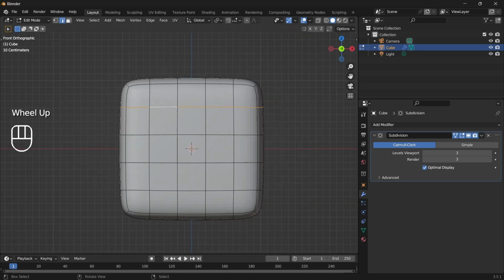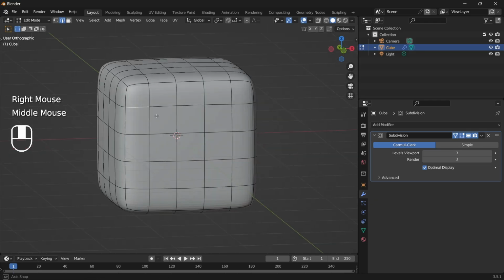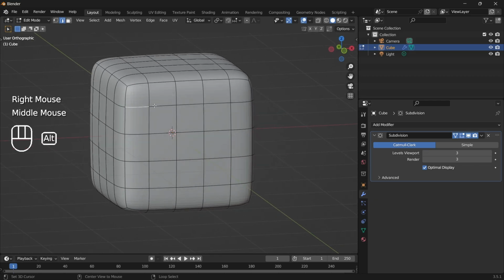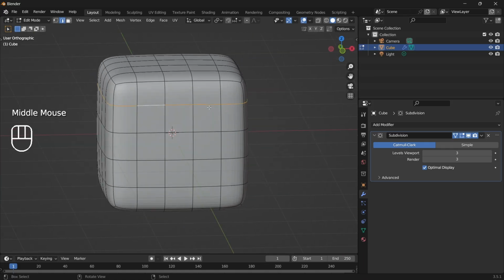One of the rules is that if edges are closer to each other, if there's a corner, then this corner becomes more sharp. In order to ring select, I hold Alt and right click, and it selects a ring of edges around our cube. You'll want to learn that later on. It's a very useful action. Alt, right click to ring select.